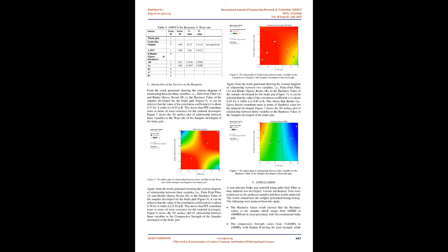Standard masses were added to the mass hanger until the lining began to slide along the surface of the steel plane. The coefficient of friction is the ratio of frictional force, equivalent to mass at hanger to initiate sliding, to the normal reaction, weight of brake lining. Equation 3.2 was used to calculate the coefficient of friction between the linings and steel.